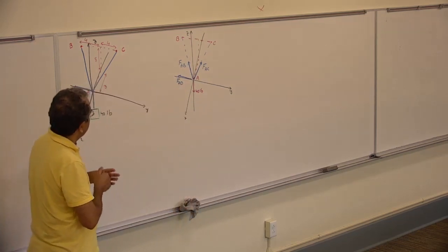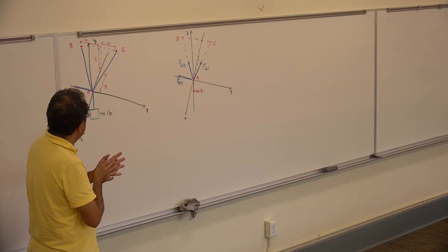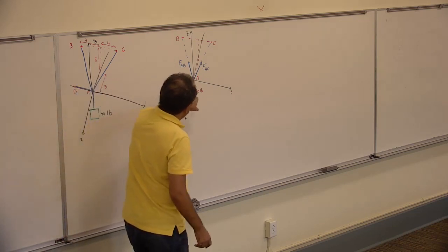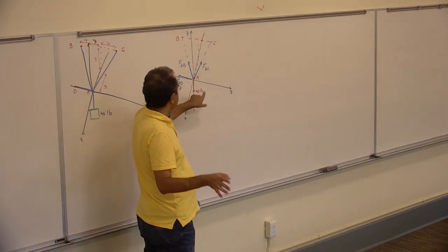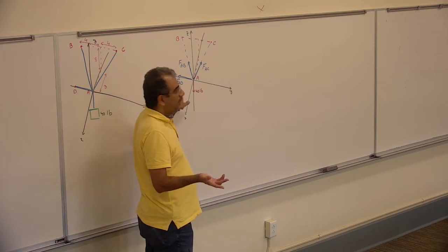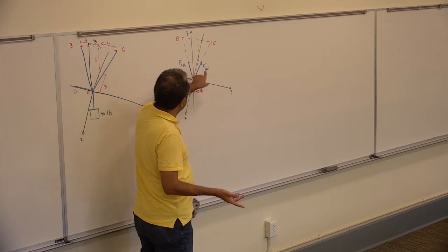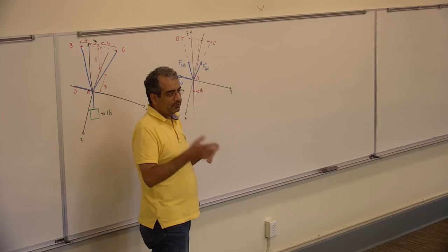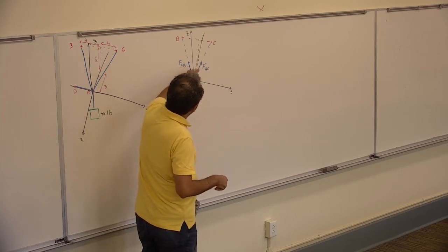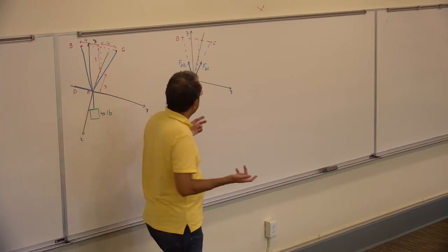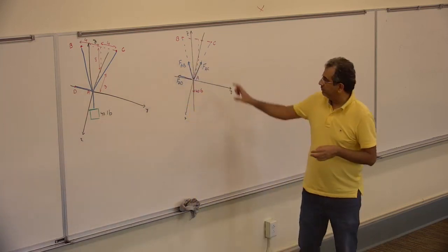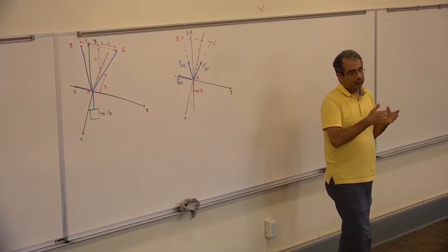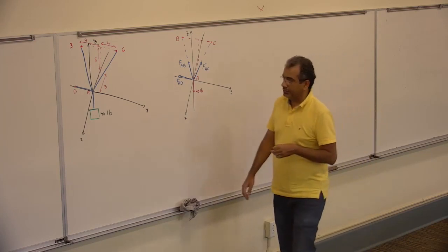So I have to find out these forces. Again, look at that FAC and FAB. The 40 pounds is on the axis. The FAD is on the axis. If I could write these two on the XYZ axis, it would be easy. So sigma of x is 0, sigma of y is 0, sigma of z is 0. But here, I don't know those. I cannot write them on the x, y, or z axis. These two, I cannot find their components on x, y, or z axis. So I have to go and make them Cartesian.